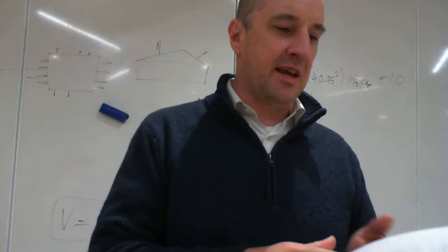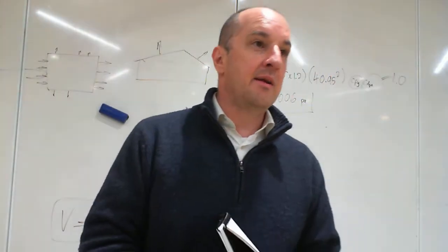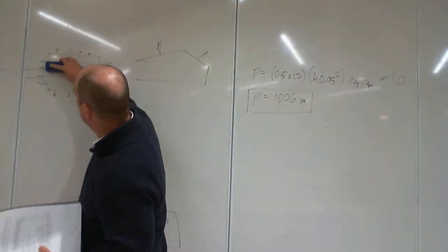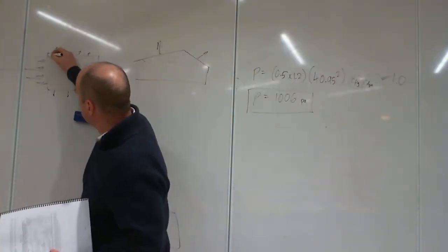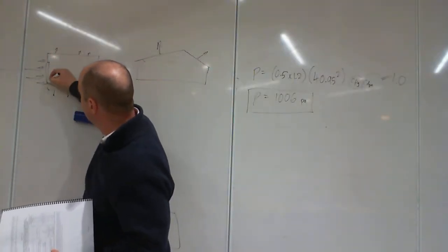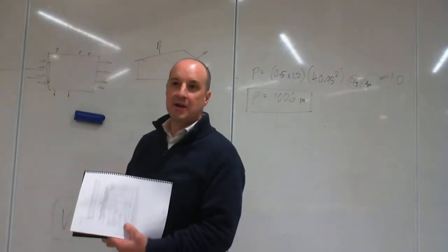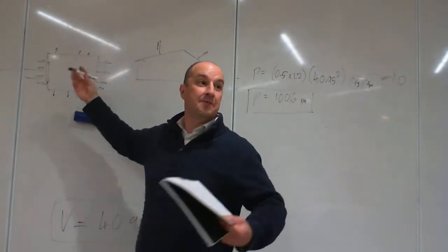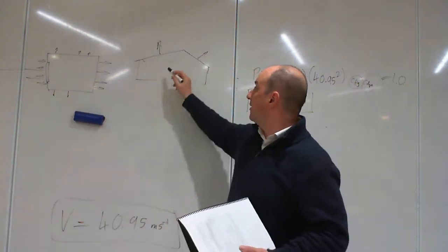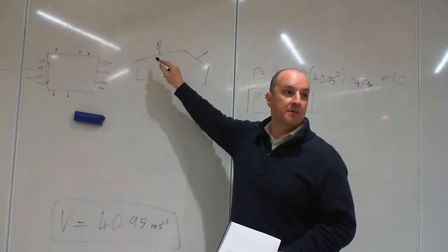And so, for example, table 5.1a is about the internal pressure, and it makes a difference if you have a big garage door there, okay, and that's all sealed up. You get a positive internal pressure where your building basically inflates. And you've got to combine that with the uplift of the wind going over the roof.